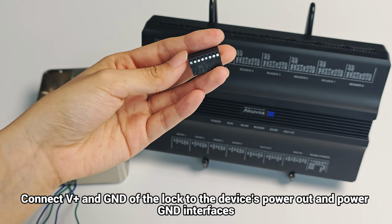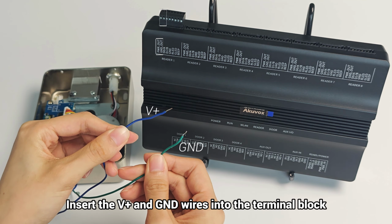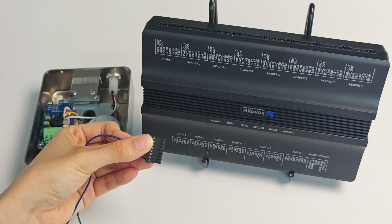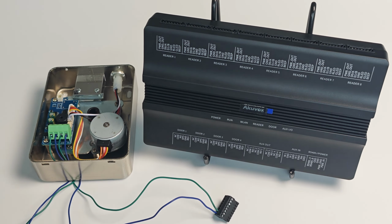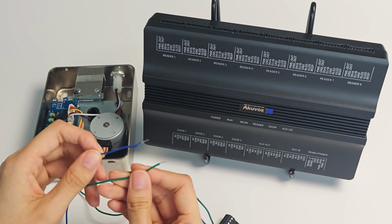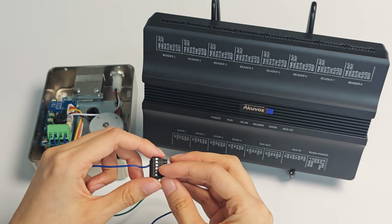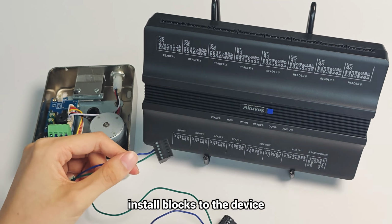Connect V+ and GND of the lock to the device's power out and power GND interfaces. Insert the V+ and GND wires into the terminal block. Ensure connections are secure. Connect L and L+ to the device's COM and NO interfaces. Insert the wires into the terminal block. Then, install blocks to the device.